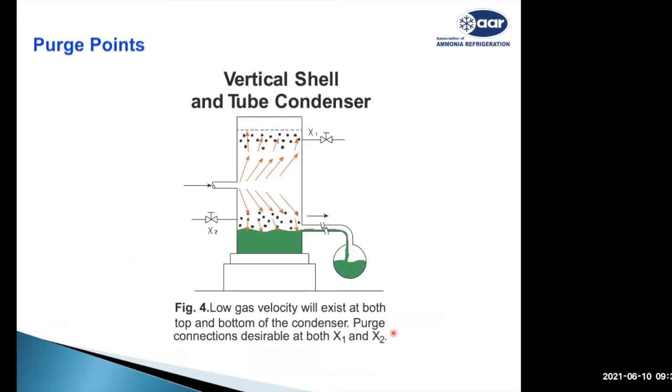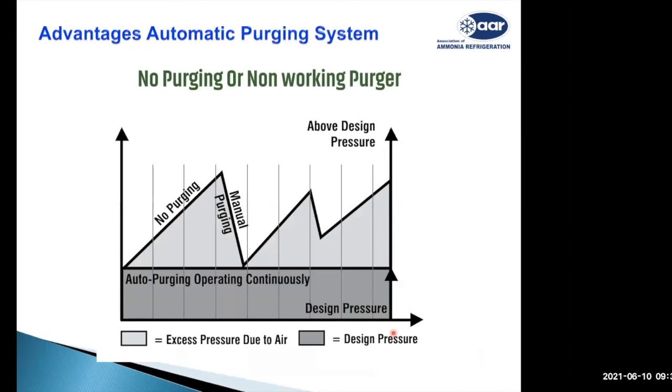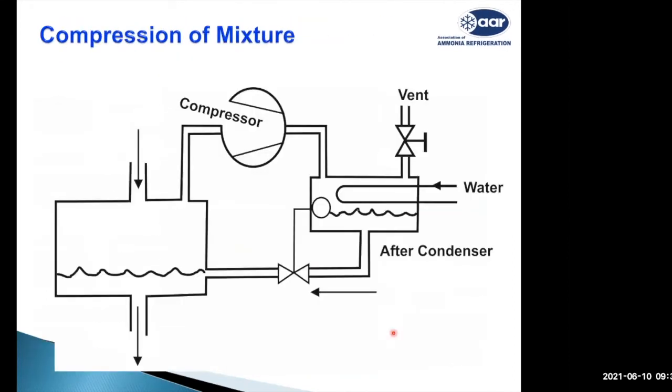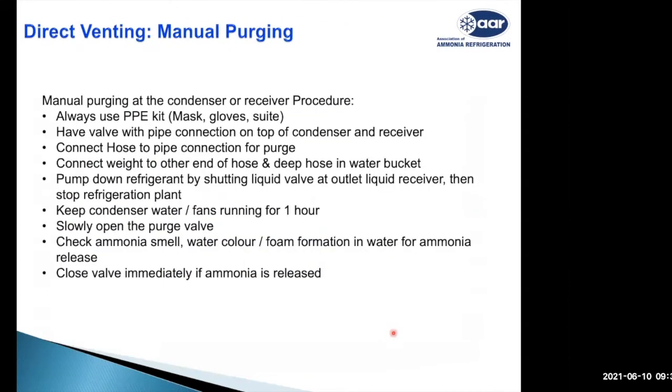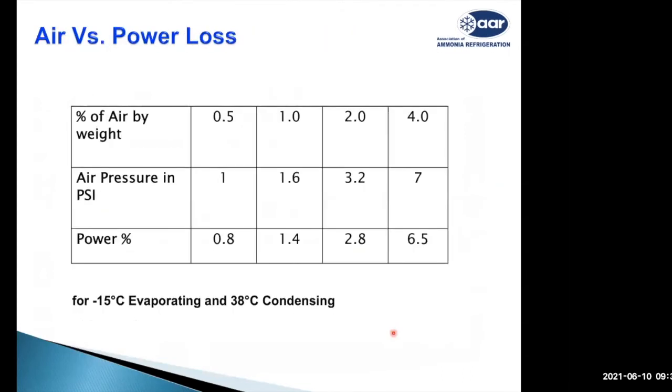One is that when my plant is being pressure tested, there is a possibility that the proper vacuum is not being done. When that proper vacuuming is not done, whatever air has entered into the system remains in the plant.